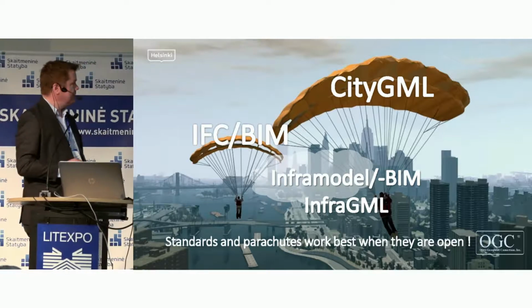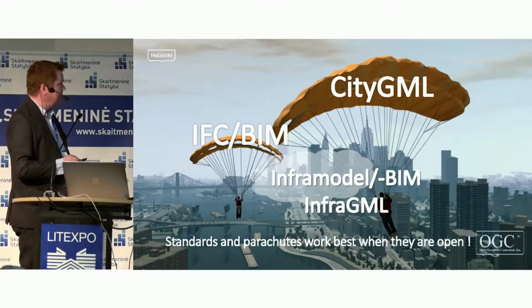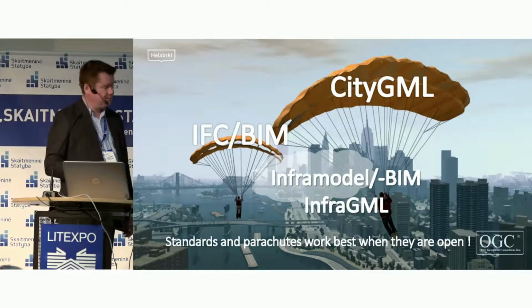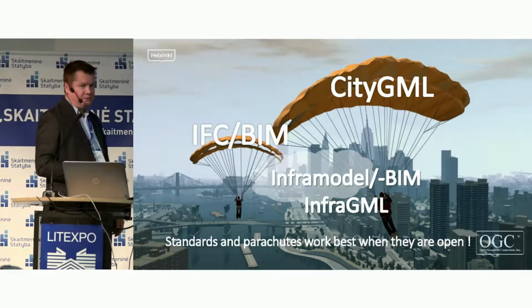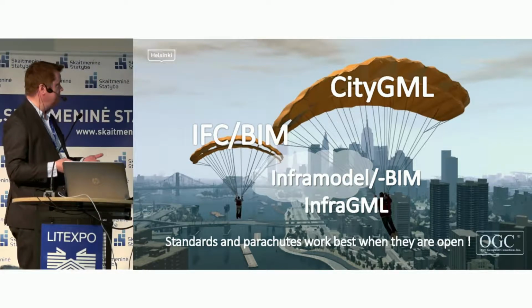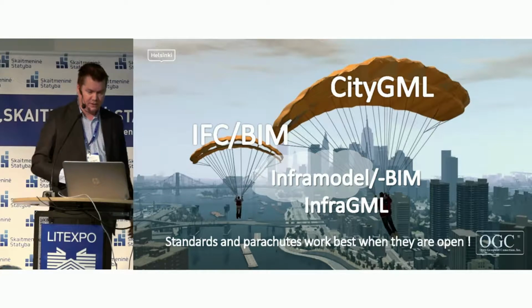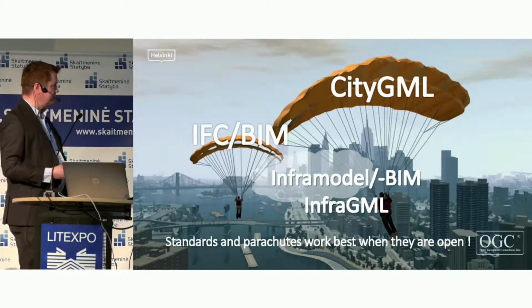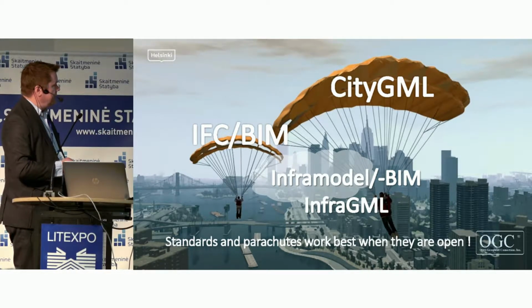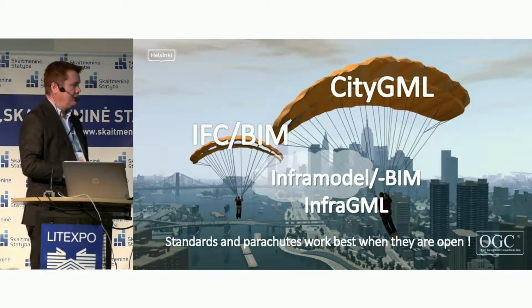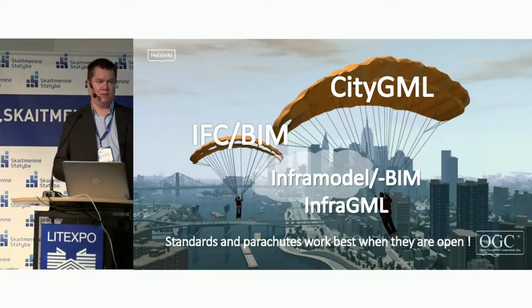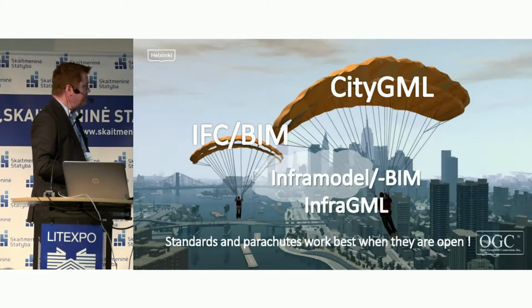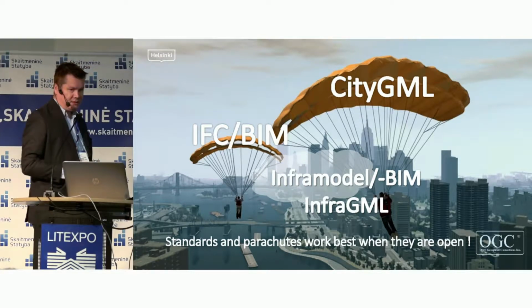Open standards were the starting point in the Helsinki city model. CityGML is a standard developed by OGC. It's an XML-based standard. They're also using IFC, which is a buildingSMART standard mostly for buildings, but in the future it will be a standard for infrastructure too. There are development projects, IFC Rail, IFC Road, IFC Alignment, IFC Bridge, for infrastructure. They also use the InfraModel standard. InfraModel is a developed version of the LandXML standard, developed further in Finland to have additional information. Also at European level there is the InfraGML standard and some other standards.